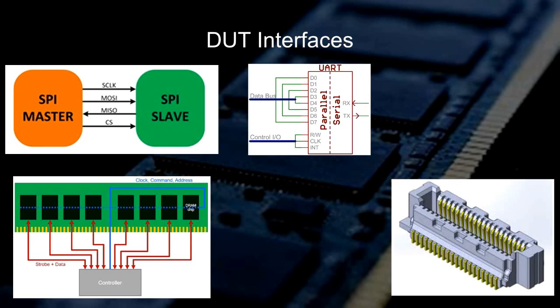The memory testing for each of the parts followed a similar testing pattern as is described in MemTest86. While MemTest86 itself wasn't used, parts of it and examples of it were used in the memory testing for the DUTs. Now the difference in the DUTs is that the SPI NOR flash and the NAND flash would be written to by paging, whereas the DDR RAM would be written to every 32 bits, meaning that a write sequence would occur in which the processor would write 32 bits to the DDR and then move on to the next address and write 32 more bits, and so on and so forth.